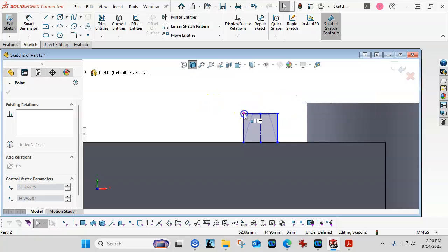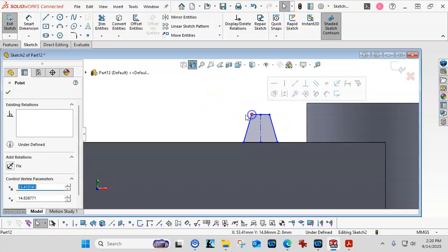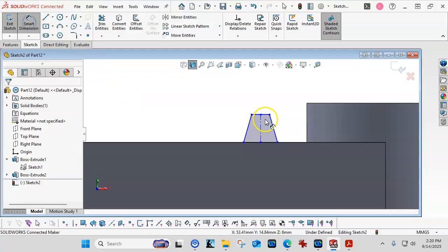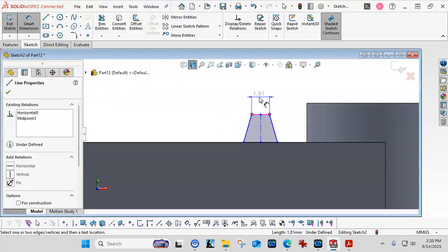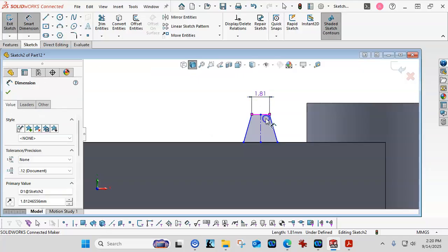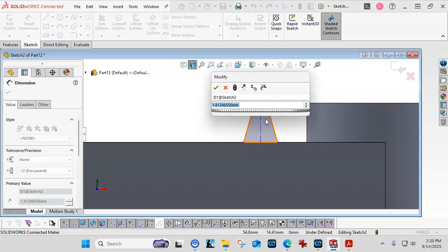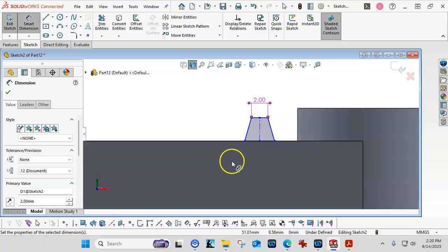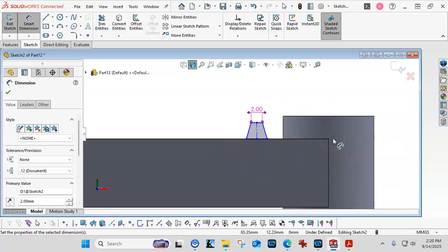All right, so what that's going to do is establish the symmetry that we're going to be able to create that geometry. So we said 2 millimeters across the top. And the 18 millimeters is another interesting case, because the cylinder where it passes through that plane will generate what's called a silhouette edge. And anything that's projectable into the plane that you're sketching in is valid geometry.